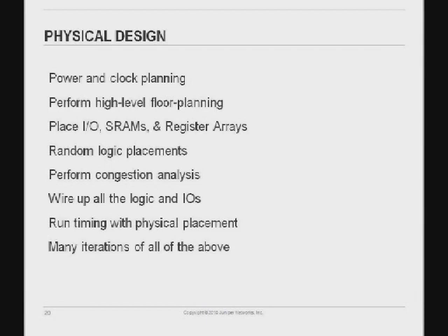And then if it doesn't work, we have to go back. And then after we determine the placement is reasonable enough, we wire them up. And then of course, we run timing every step of the way. And with the fixed physical placement, we extract the parasitics. Those are called parasitics, the resistance and the capacitance of the physical wires, and run timing simulations with the gates to make sure they work to the frequency we desired. And we do many, many, many iterations of the above.